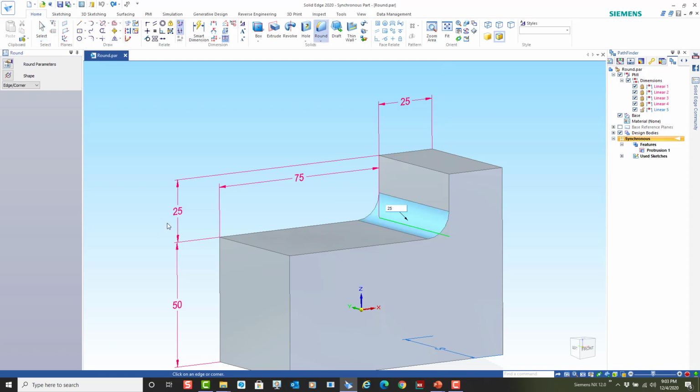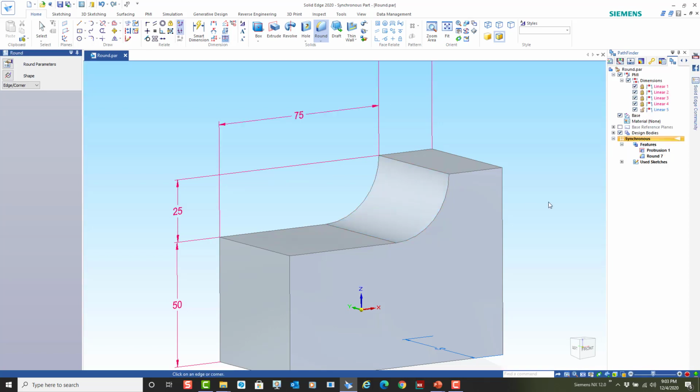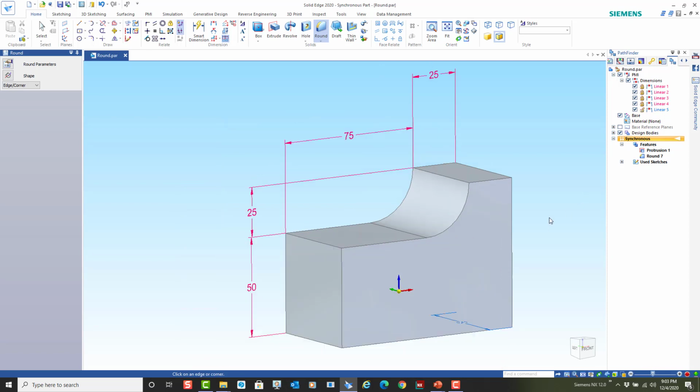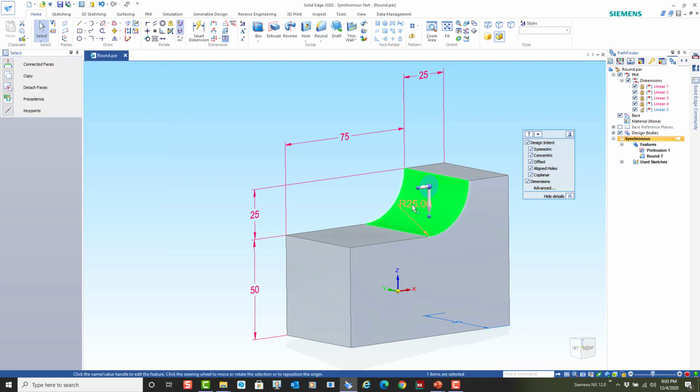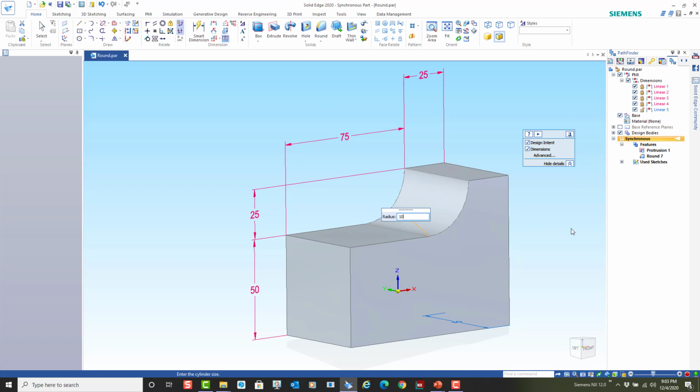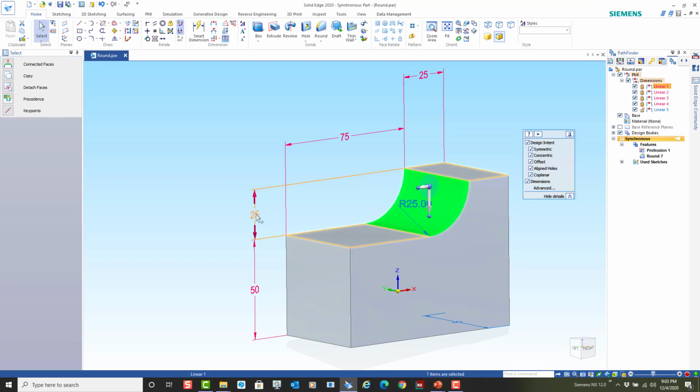Now you'll notice that 25 millimeters is the height of that wall. So if I place that in, that face from that wall disappears. It's totally consumed. So now the system doesn't even remember that that face was ever there. It totally forgets it. If I go in later and try to change this value back to 10, you notice I get an error. It doesn't know how to recompute this, especially since these are locked.